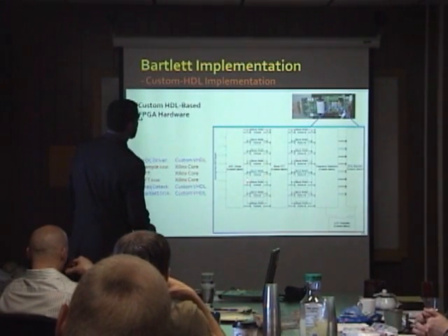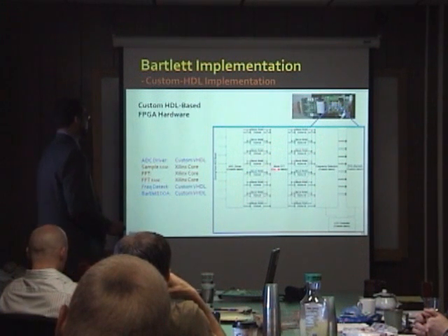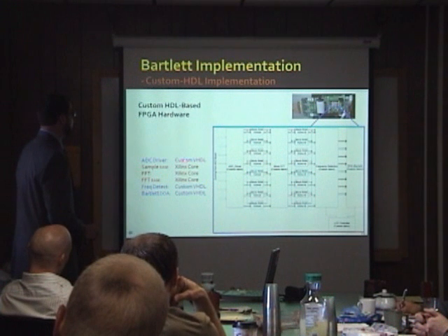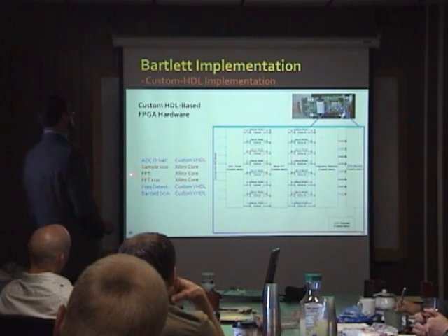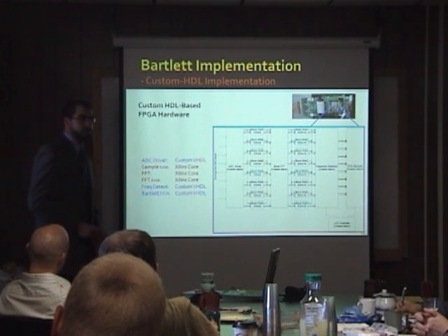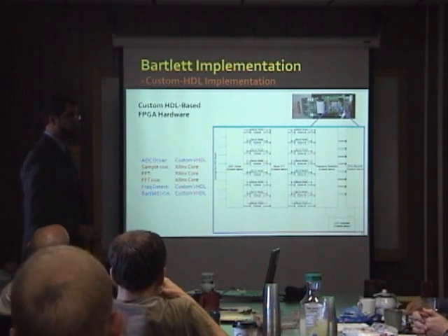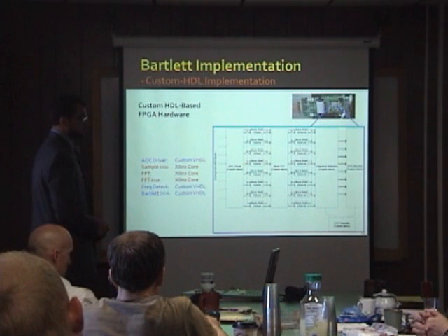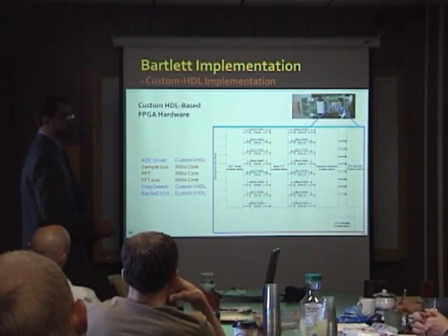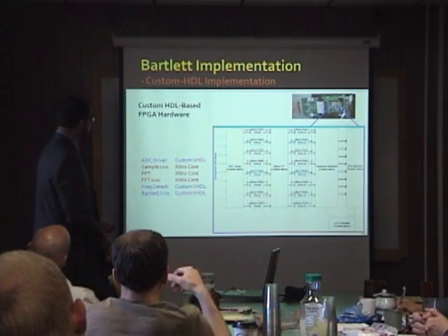So here's a picture again for the hardware implementation. The ADC driver was written in custom VHDL. We generated the sample RAM and the FFT RAM using Xilinx Core Generator to save development time. And since it's provided and optimized, the frequency detection and DOA parts were designed in custom hardware.